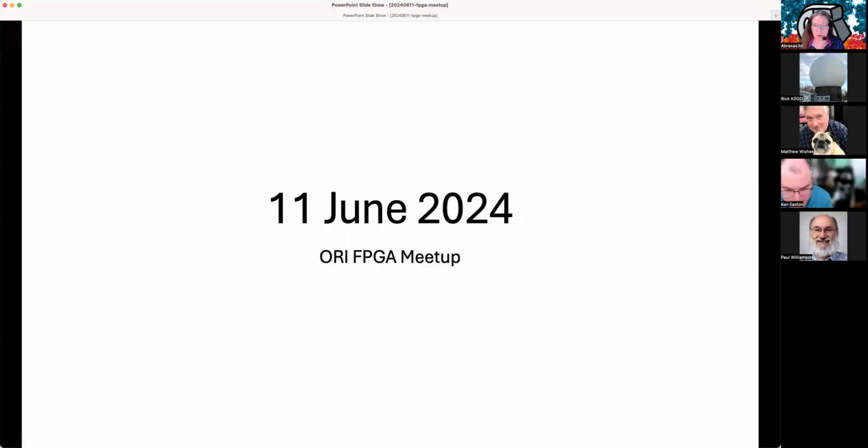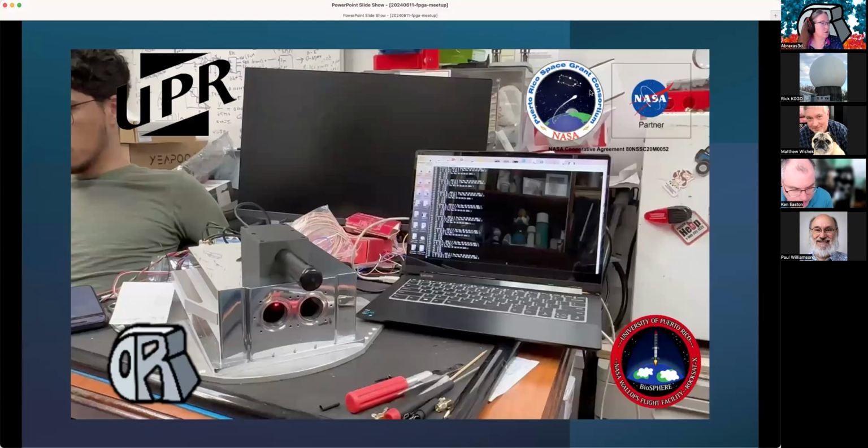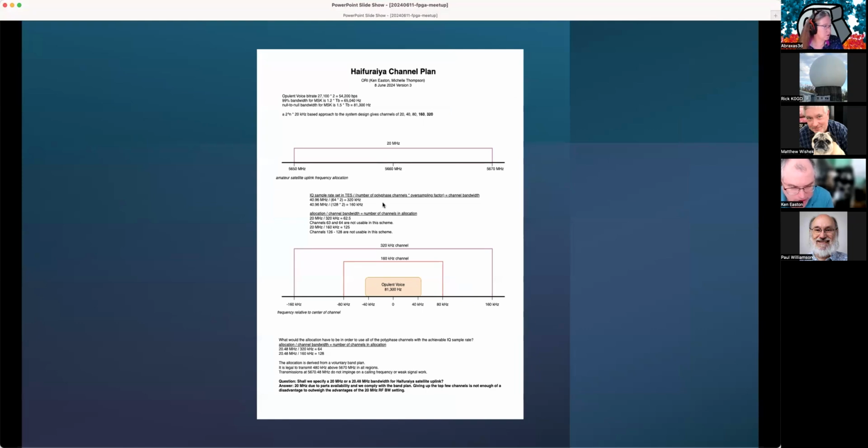I think the 9009 is a little more geared towards even wider bandwidth designs. So as you bring it down to the 20 megahertz range, there's a variety of restrictions that get close to the minimums, but we've got something that at least builds. We just need to plug that now into the framework. Basically, it's a radio configuration, and we have the bit file that has the polyphase input. So in theory, we're pretty close to being able to feed live samples in. So that's about it.